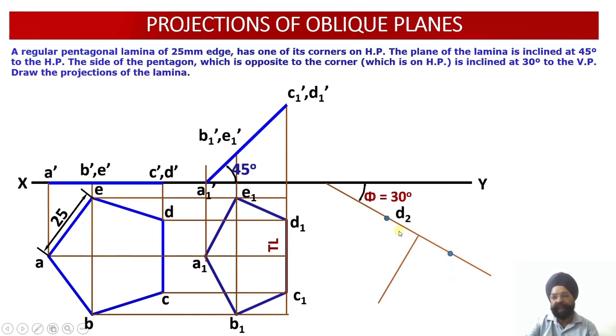So just see, here we have got these 5 points. So this is 0.1, 0.2, 0.3, 0.4 and 0.5. Corresponding to 0.1 and 5, you measure this distance of B1 and E1. So just see, we have measured the distance of B1 and E1 over here, and corresponding to 0.2 and 4 there is 0 vertical distance, and corresponding to 0.3 measure the distance of A1 from this locus line.